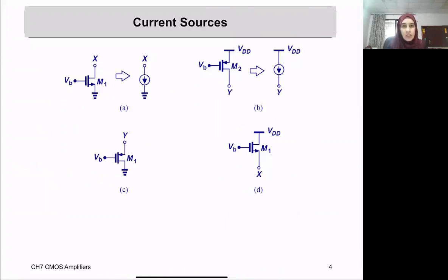Now you remember the voltage headroom problem. We said that the gain depends on the load resistor, which is RD. So in order to increase my gain, I need to have a larger RD. But what's the risk in doing so? I might be leaving the saturation region. Why? Because VDS is going to be affected by the voltage drop across this resistor RD. So if I have a larger RD, this means I have a larger voltage drop across it, and I might be more prone to leave the saturation region.